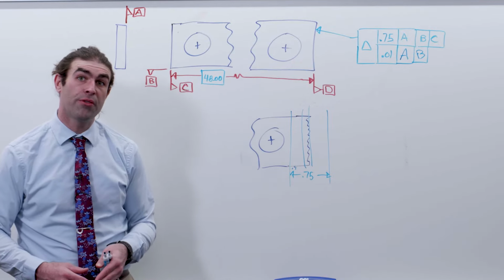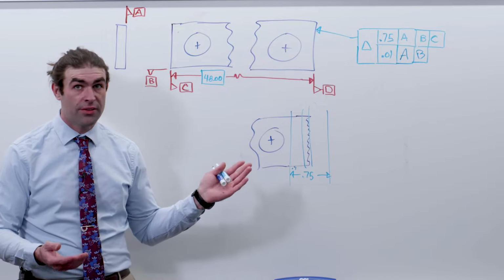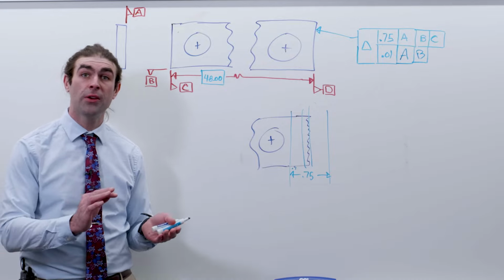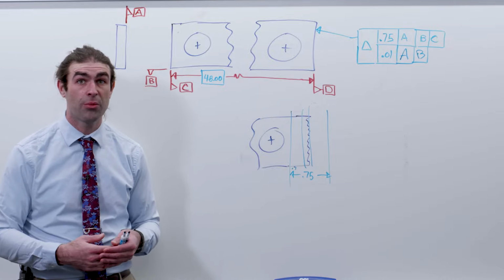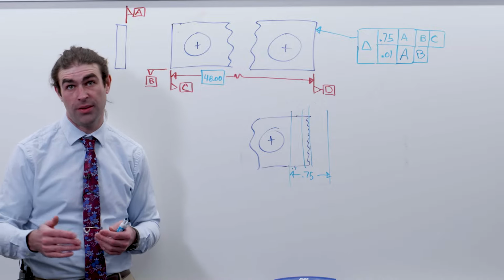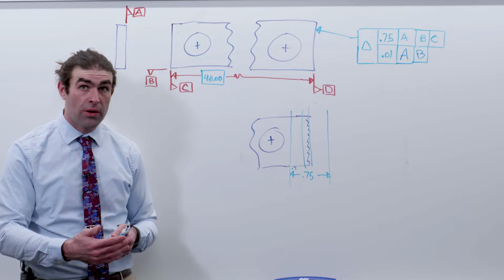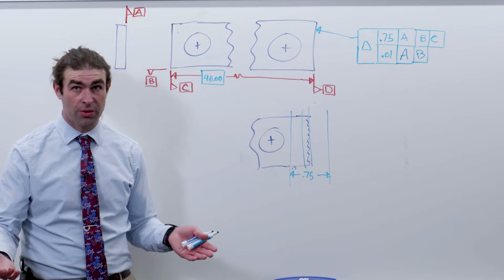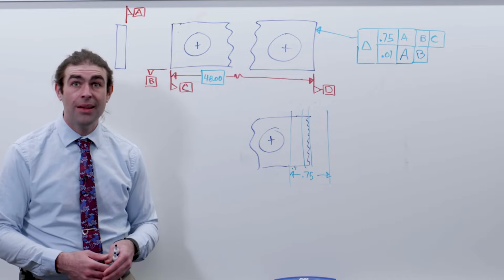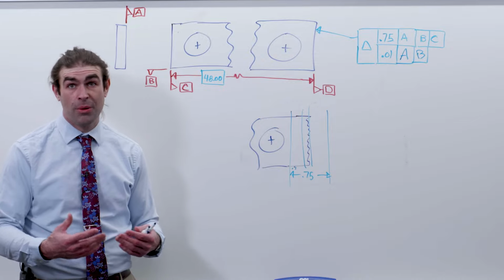And if I didn't mention it before, the difference between the composite and the two single segments is essentially nothing in this case. With the two single segments, you can have the datums in a different order if you needed that for some reason, whereas with the composite, they need to be in the same order and the same material condition. So if it's a different material condition, it's a different datum reference frame because you're calling out the datum in a different way. So that's it for this video, just an overview of profile and some of the applications.